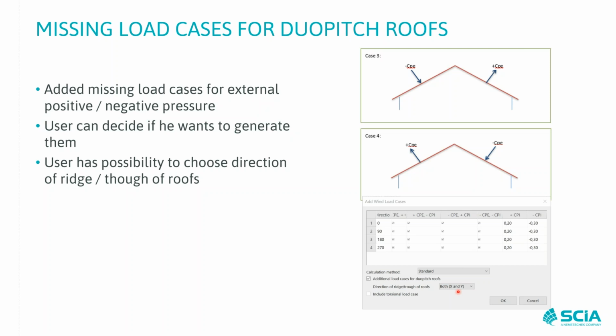If you have a more complicated structure like a T or L, you can choose, as I have here now, to apply this possibility in both directions, so that I have generated these load cases for the dual pitch roofs which I have in my structure.